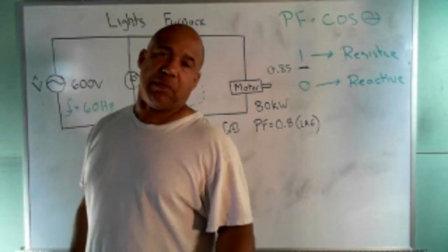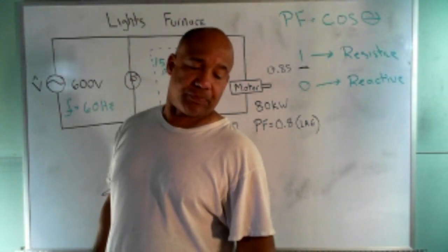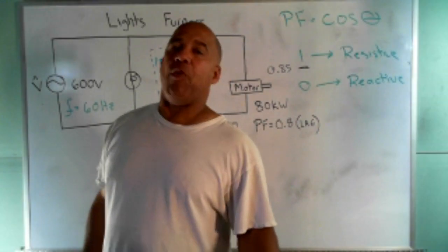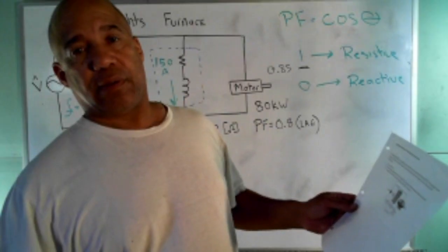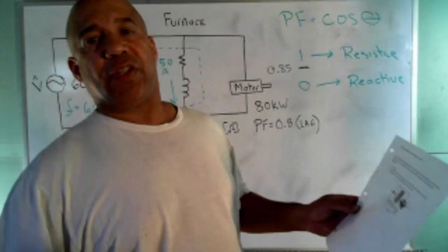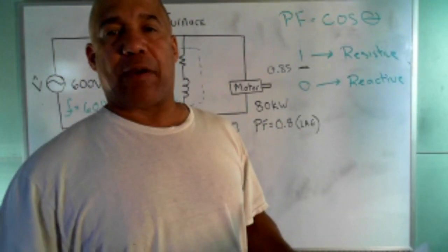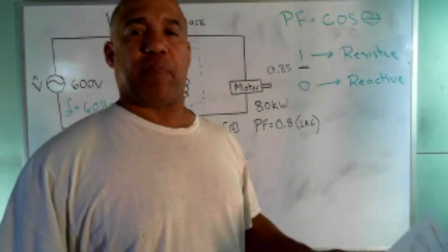The first part you should be able to do by yourself, no problem. Now, I want to recommend something, guys. This is called power factor correction. When you're doing this, always use power triangles to solve the problem. So try to work off the power triangle.